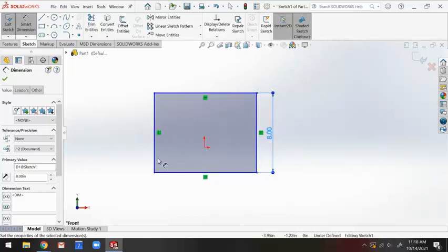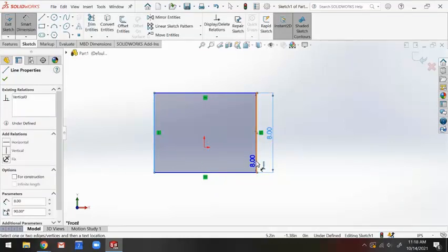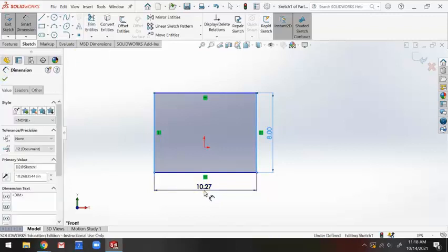Control-1 to get it so it fits better. I'm going to click on this bar and then this one. So sometimes what you can do is you can take two objects, 2 points, 2 lines, 2 curves, whatever, and if you want to measure in between them, you click both of them with the Smart Dimension tool, and it'll allow you to pick the dimensions between those 2 lines.